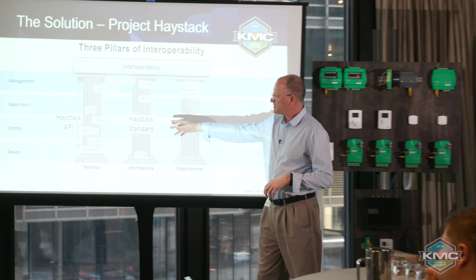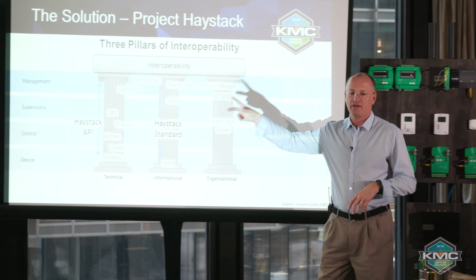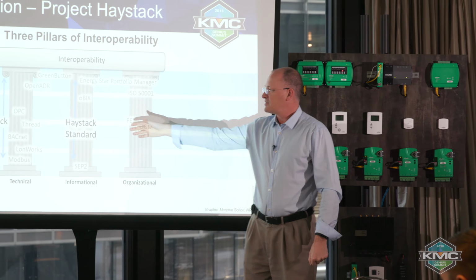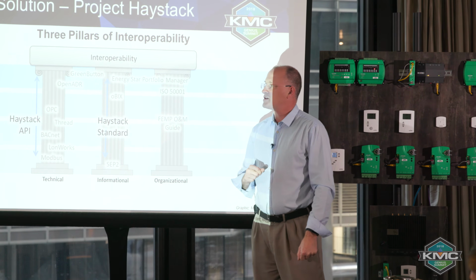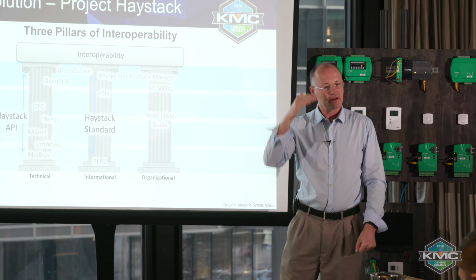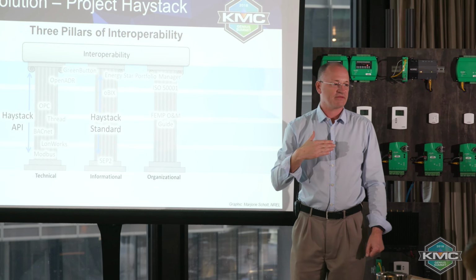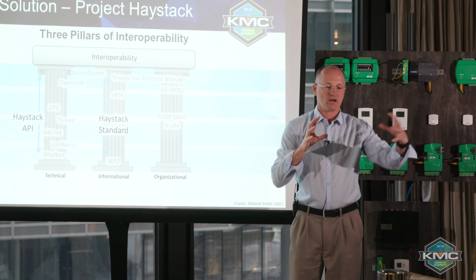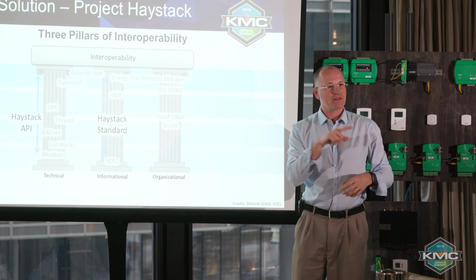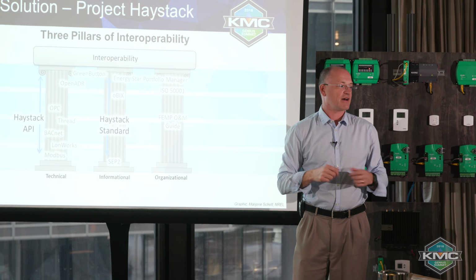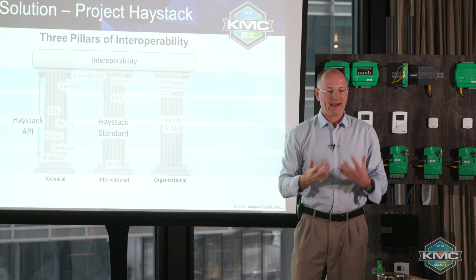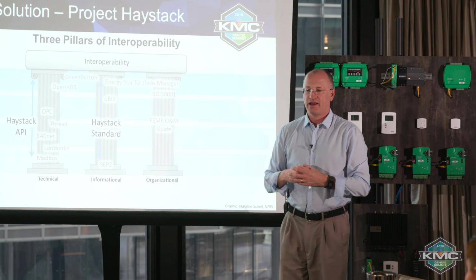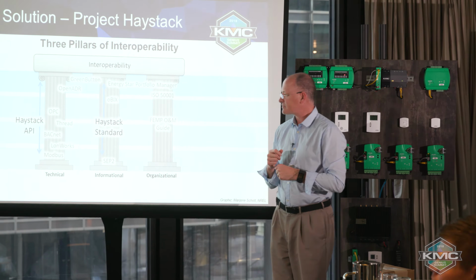Now, as far as the standard is concerned, this is where we get into the equivalent of naming conventions. If I were to drill into Project Haystack and look up an air handler, it gives some suggestions of what people have collectively come up with for the different inputs and outputs you'll find on a typical air handler, and what tags to put on those points so that any application could connect to it.